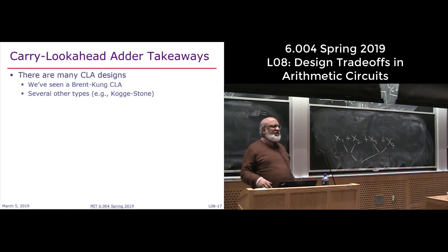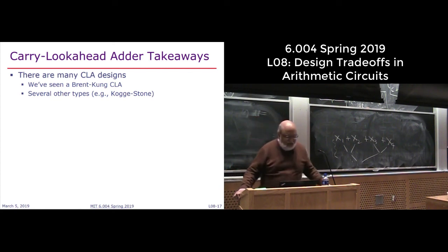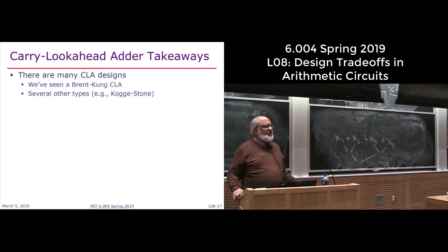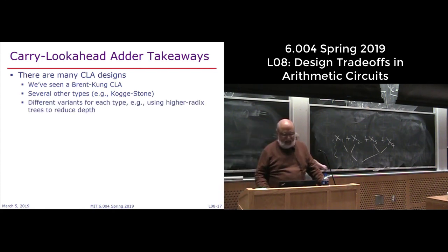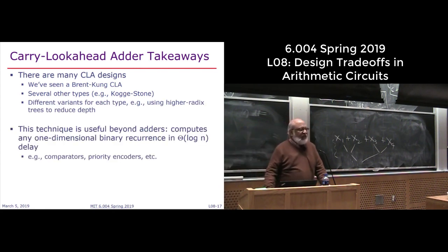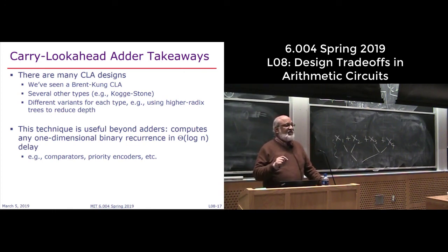Okay, so there are many different ways of connecting these carry-lookahead adders, but the idea is the same. You are always trying to capture something about generate and propagate, right? And we have seen the Brent-Kung adder, and there are other ones, the Kogge-Stone adder, and they all try to improve, so it takes less hardware, but they all have the log n property. We can't do it better than log n over there. The reason why you should try to understand this technique is it's not just for adders. Any associative operator you have, any binary associative operator, this idea will work over there.